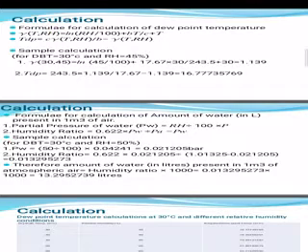The above two formulas are used to calculate the dew point temperature for different atmospheric conditions at which the device may be subjected to operate. First we have got the dew point temperature, that is 16.77 degrees Celsius, using the data, that is dry bulb temperature at 30 degrees Celsius and relative humidity at 45%.